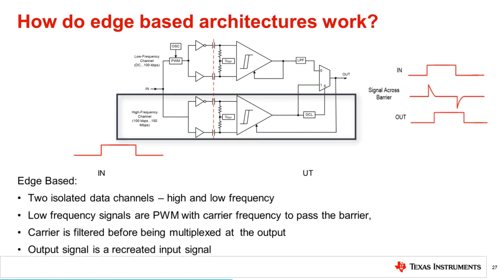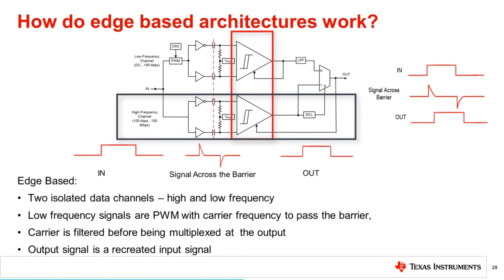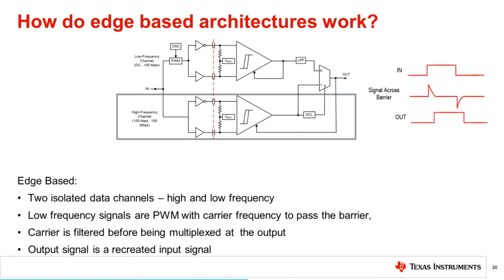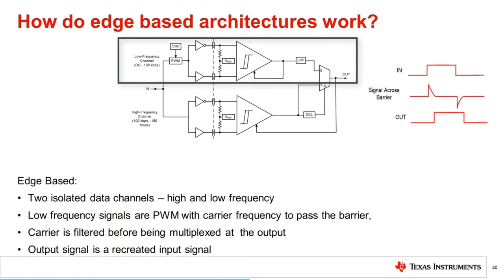A single-ended input signal entering the high-frequency channel is split into differential signal via the inverter gate at the input. The capacitor-resistor networks then differentiate the signal into transient pulses, and decision logic at the output of the high-frequency channel comparator measures the durations between signal transients. If the duration between two consecutive transients exceeds a certain time limit, as in the case of a low-frequency signal, the decision logic forces the output multiplexer to switch from high-frequency to low-frequency channel.